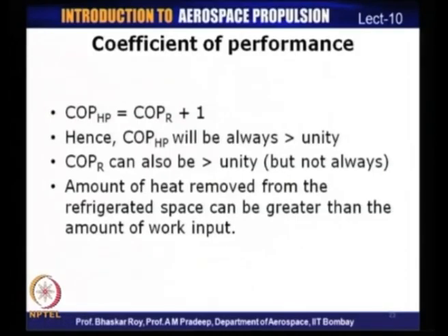From these two equations, we can actually prove that COP of a heat pump is equal to COP of a refrigerator plus 1. This means that the COP of a heat pump will always be greater than unity, and the COP of a refrigerator, on the other hand, can also be greater than unity, but it is not always the case.